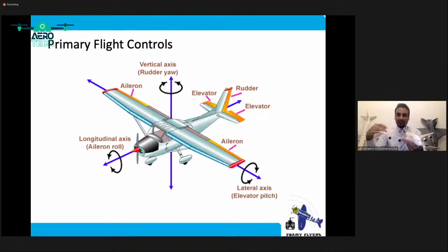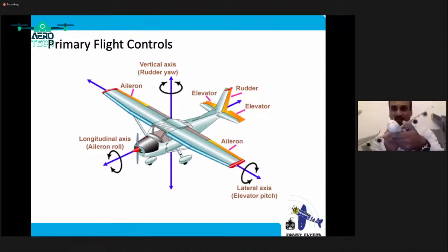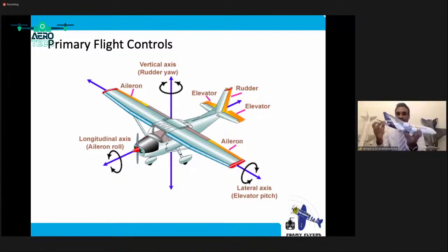Let's say if this one is pointing upwards, that means the aileron surface is moving upwards. That means it's pushing this side of the wing down, but this side is moving downwards, which means it's pushing this way. So what ailerons do is help to rotate the aircraft, like bank the aircraft left or right, right? So elevator, up and down; ailerons, right or left, banking.